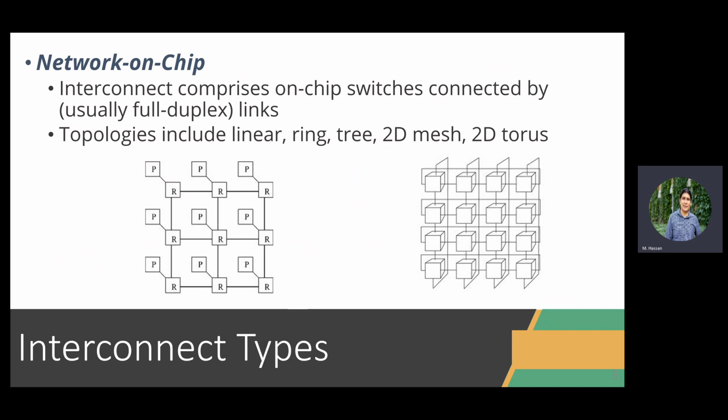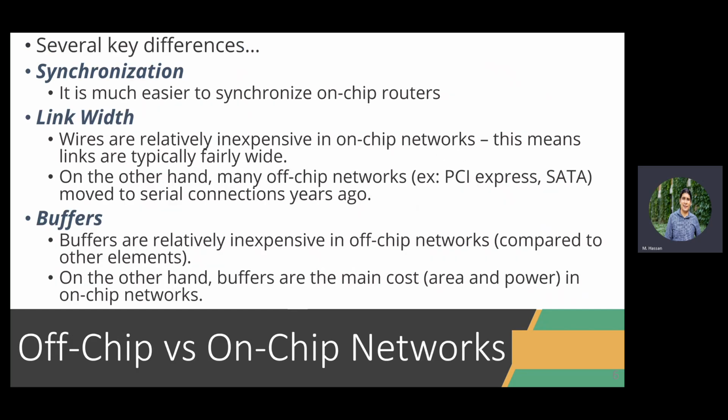There is what we call a ring, which is very common in Xeon Intel processors, for example. Instead of having this complex interaction, I only have a ring between all the processors. So it's a circular bus, in a sense. And we can have a tree, we can have a mesh, a 2D mesh, a torus. So there are multiple network connection architectures. Not the focus of that course.